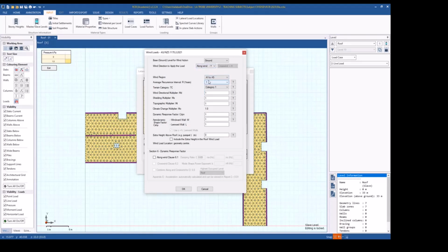I trust this one, A1 to A5, if you look at Structural Toolkit. So this is recorded, and for the category, make sure we choose the same as whatever we had in Structural Toolkit, because the software will end up calculating those pressures. Remember the pressures you did in the tables? It will automatically calculate them and apply them on the building.